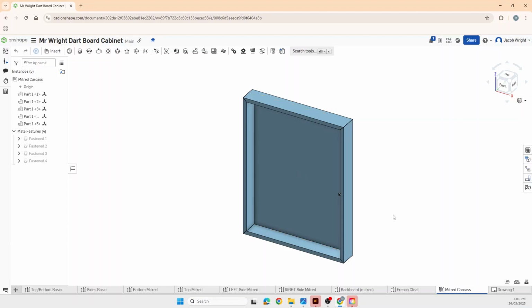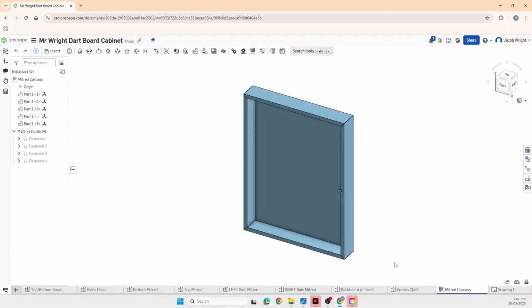So the first thing I generally like to do is draw a small sketch on paper with those features that I'm looking at adding. And then once I've got that sketch with some basic dimensions and spacings, I can then use that sketch to help me come in here and add those features to this cabinet. So we're not actually going to edit this assembly. This assembly will stay on its own. We're going to go in and edit each individual part by clicking on those tabs along the bottom here, editing the part. And once you edit that part, it will automatically update here in this assembly.